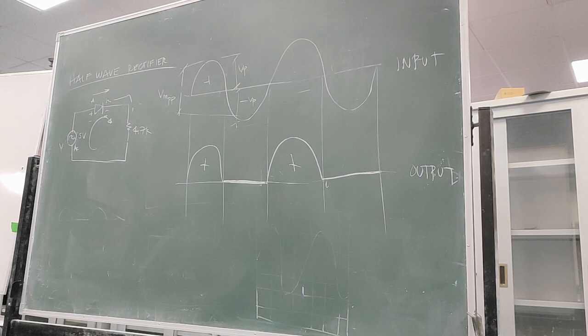You need to calculate. I will teach you how to get the value based on the waveform on the oscilloscope. It will be per division. You will find there the Y divisions in the table. You will find the table, and you find that V in Y voltage per division. Also the same thing with the time. Okay, the time.